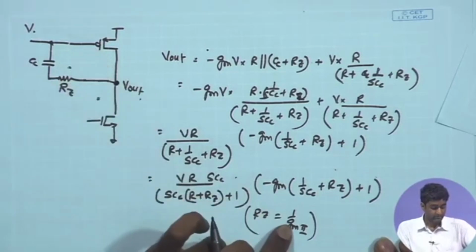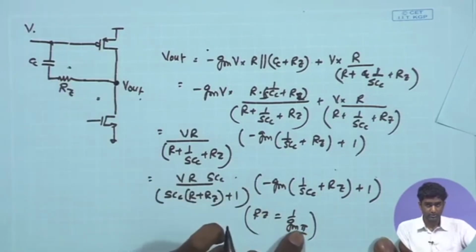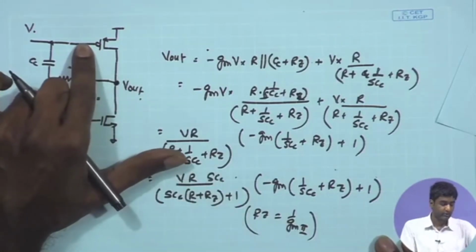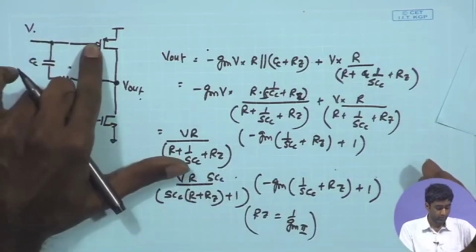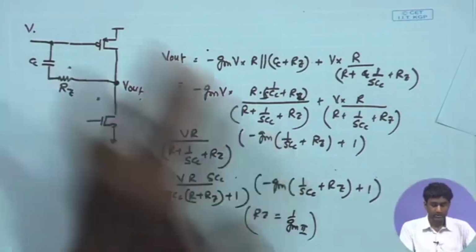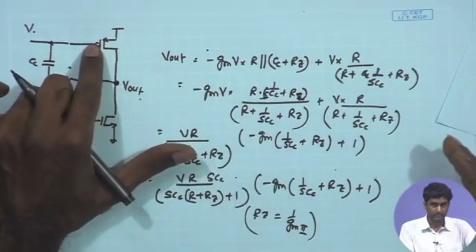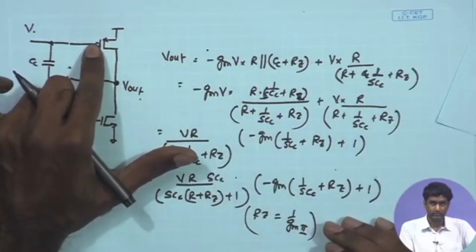However, gm is not a very well defined quantity, it can vary significantly more widely. You can have plus minus 50% or even 100% change in the gm. So, if in simulation you are setting up this value of gm to be 10 to the power of minus 4, in the actual design you may get a value which is 2x or 50% of that.